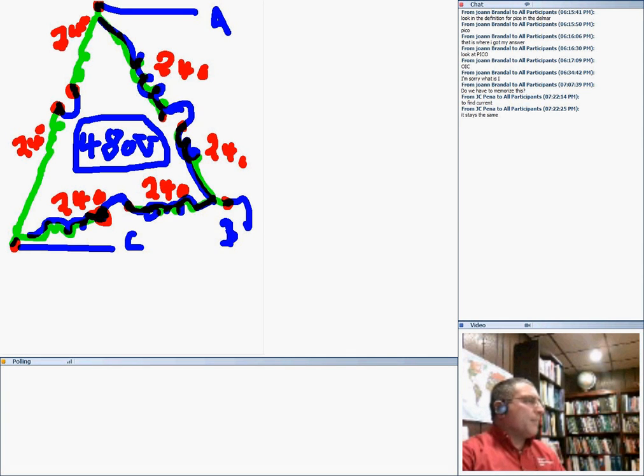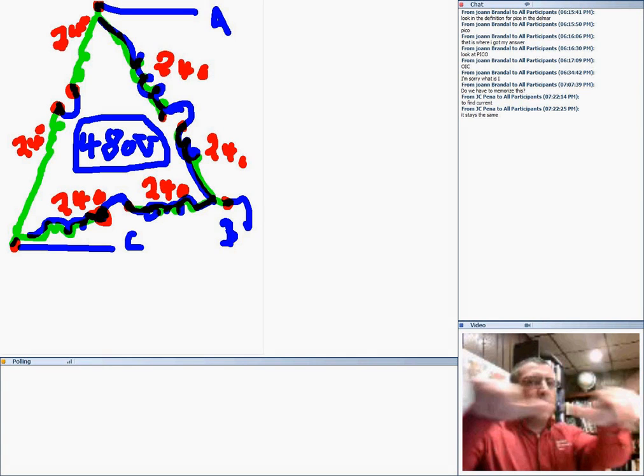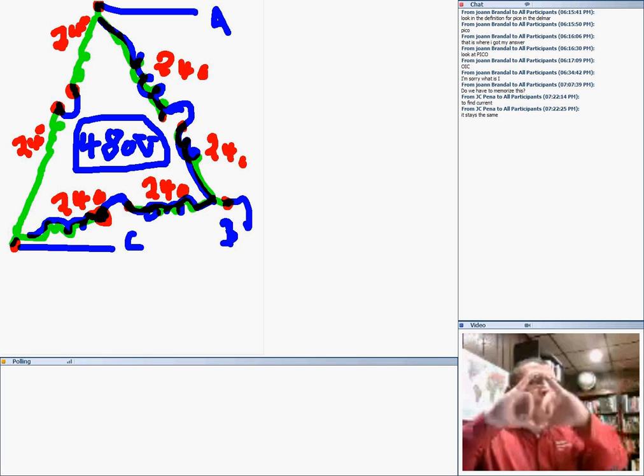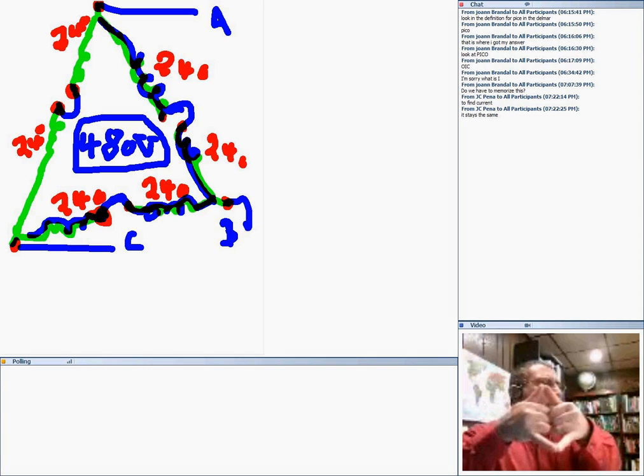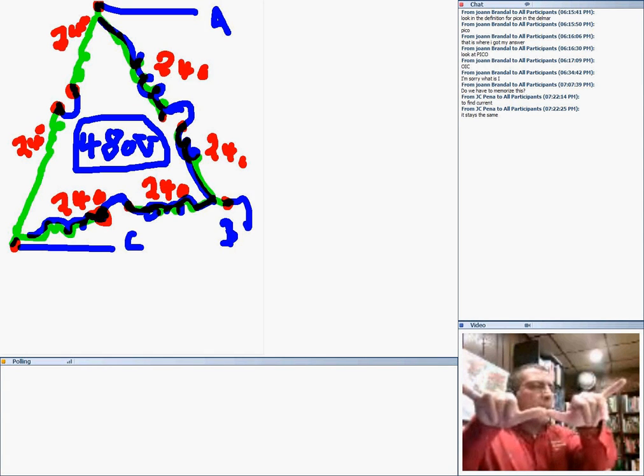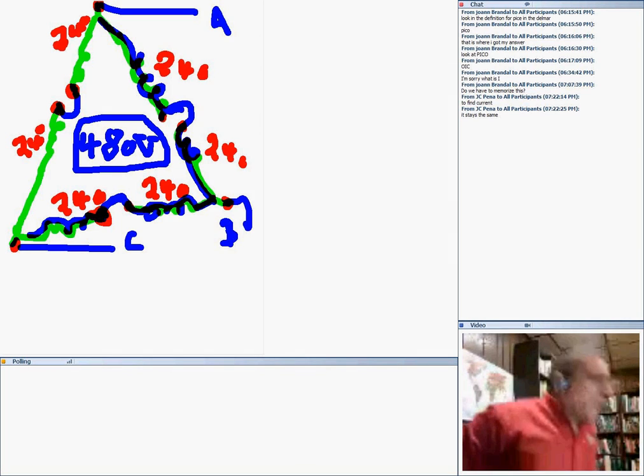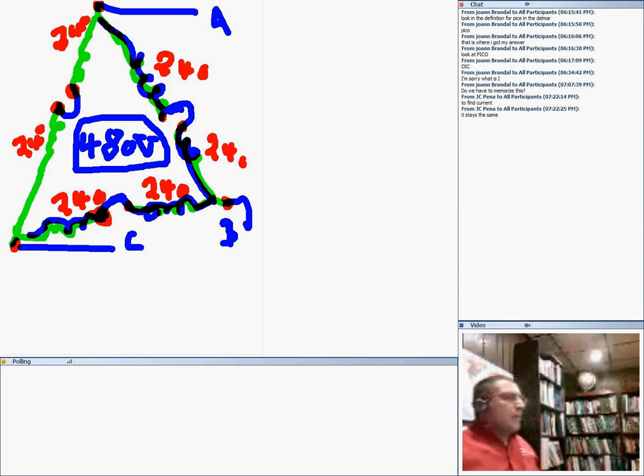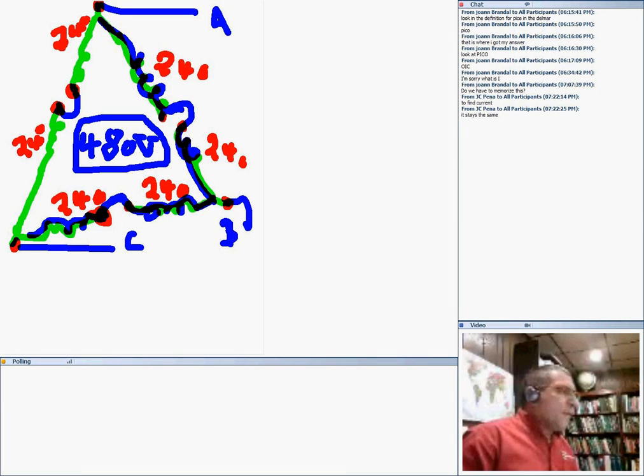The question is about this. You will spend some time being tested on this for your journeyman exam and master: how to connect coils in series to get you a higher voltage. Now, Jacob, my friend, if you put two coils in series, you always add the voltage. If you put them in parallel, the voltage stays the same. In series, add the voltage. So if each one of them is 240, 240 plus 240, you put them in series, they become rated for 480. And then you can build any voltage basically you want. That's for motors.